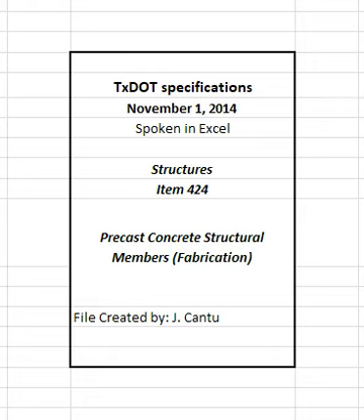Heat the aggregate and the water when needed to produce the minimum concrete placement temperature of 50 degrees Fahrenheit, but do not allow the water temperature to exceed 180 degrees Fahrenheit or the aggregate temperature to exceed 150 degrees Fahrenheit. Heat the aggregate uniformly to eliminate overheated areas in the stockpile that might cause flash set of the cement, and provide an aggregate and water mixture temperature between 50 degrees Fahrenheit and 85 degrees Fahrenheit before introduction of the cement.